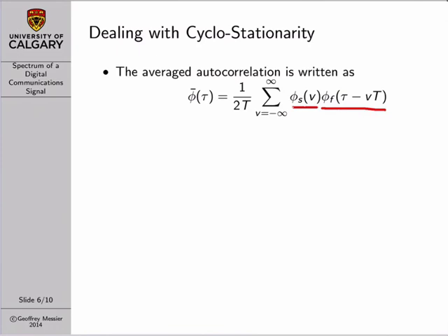And so if we look at the equation that we have left, this equation is basically equal to a convolution. This summation is essentially equivalent to a convolution where we're convolving the autocorrelation of the signal vectors with the correlation of the pulse shapes, or of the basis functions. And that's basically the end of the derivation. So we now have the autocorrelation function that we set out to find. And the last step is to just take the Fourier transform of it.